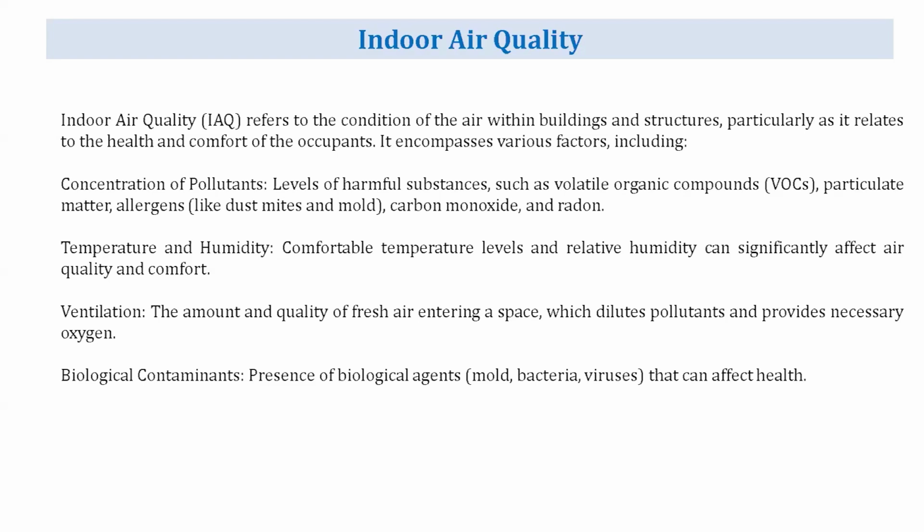In easier language, what is indoor air quality, if we categorize it as good or bad? If I say indoor air quality is bad, what are the parameters that define that it is bad? First of all, it is the concentration of pollutants, so we can call it contamination. And then temperature and humidity. You feel comfortable when the temperature is somewhere around 25 degrees. It is recommended to average 25 degrees, but you can go in the range of 22 degrees to 30 degrees, where you'll feel very comfortable.